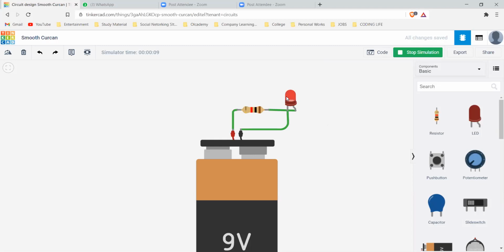So now the basic things that I would like to suggest you before you use TinkerCad. The basic thing is wires. Okay, so when you're connecting wires, TinkerCad basically gives you just green color in the beginning, but it is better to always color code your wires. The thing is, if you do not color code your wires, you will have wires going all over and you have to trace each wire where it goes.